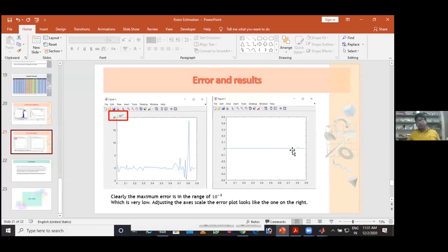If you want to implement rapidly, for rapid prototyping, you can use this controller, and you can implement those things in Simulink, and the code will be generated. That code will be imported to Code Composer Studio, and you burn it without knowing any bit settings of the register. Very quickly you can prove the concept.